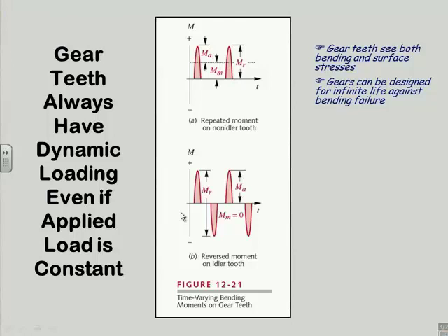That's not true of surface failure, because as we learned when we discussed that in Chapter 7, there is no equivalent endurance limit for surface loading. And if you run things together in surface loading long enough, even at relatively low stresses, eventually you'll start to pit the surface. Now, if the stresses are low, it's going to take a long time for that to happen.